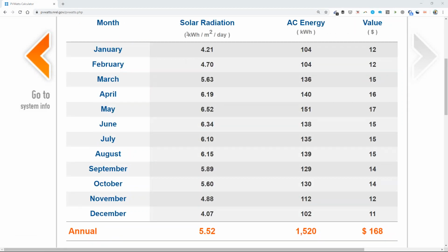we've got these. They've compressed how much sunlight is going into the 12-hour period that the sun's up, and it's saying, okay, we're going to compress it into 1,000-watt per meter squared hours. So in July, the array might be producing from 8 a.m. to 7 p.m., but out of that 11-hour slice, we've gotten 6.1 sun hours of 1,000 watts per meter squared.